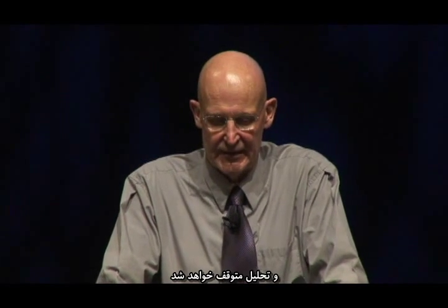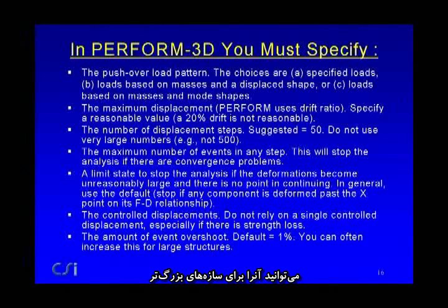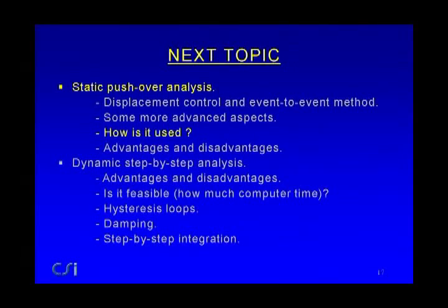And then it'll stop. And finally, the amount of event overshoot, and the default is 1%. And as I said before, you can often increase this number for large structures, and you can go as high as 20%. So next stop, we're still on static pushover analysis.